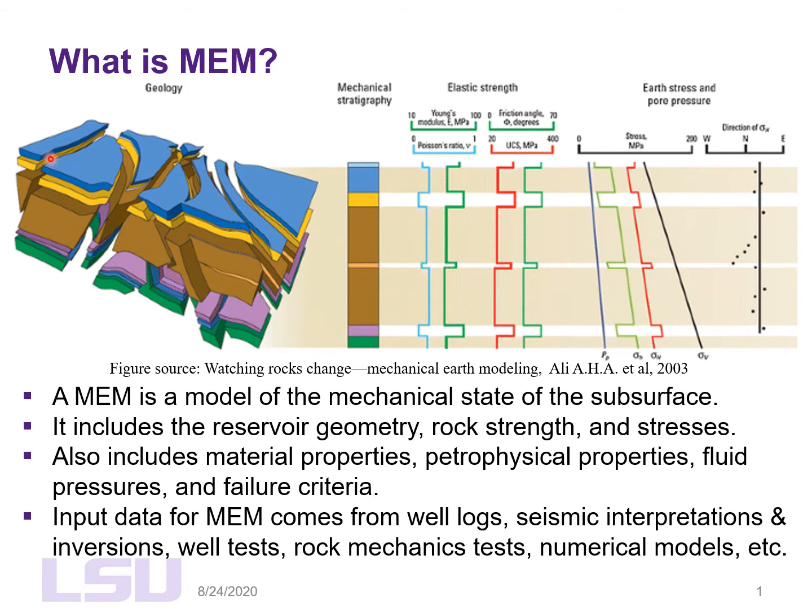And that force divided by the area through which the force acts gives you pressure or stress. So stress is force per unit area. So the force exerted by the rock mass sitting on the top of the formation of interest is the overburden stress, also referred to as the vertical stress.